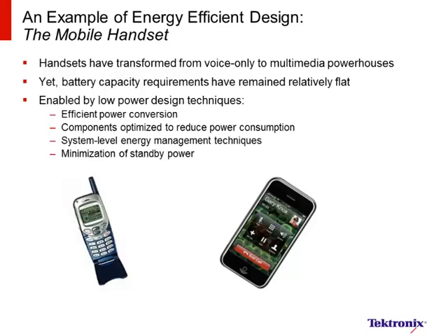Now, throughout the mobile handset, components have also been optimized to provide the lowest power usage. Displays, for example, that use specialized backlight LEDs provide power savings of up to 80% over previous types. Standby power has also been minimized. Even with low voltage, low power logic and microprocessor sleep modes, standby power consumption can significantly limit battery life and the usability of the handset.